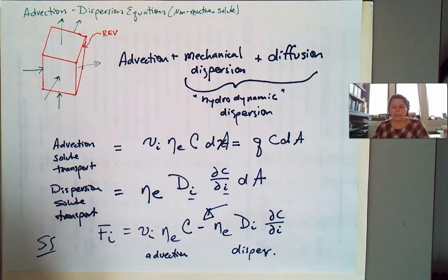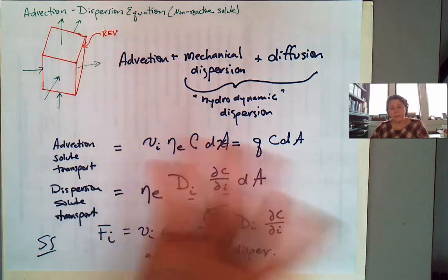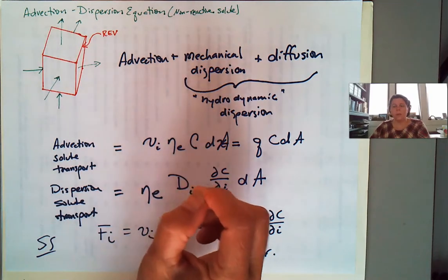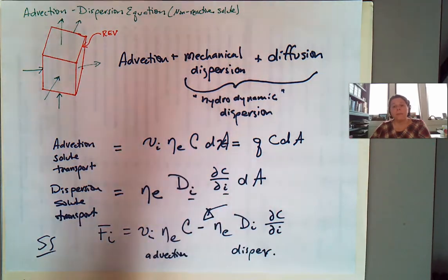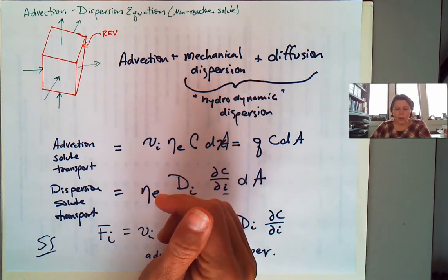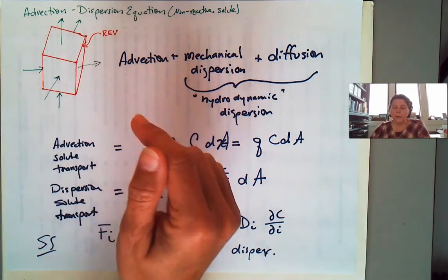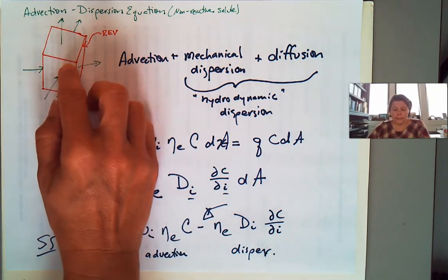Now, we apply this continuity principle to solute transfer through our representative elemental volume. There is conservation of mass, so what comes in has to come out or is stuck behind, but we don't lose it. We'll get to when solutes actually disappear, where they're being transformed, in the next section after we get through this. So the change in solute flux through a representative elemental volume, as it's going through here and coming out over here, is the change in the storage. It's being stored inside of here.